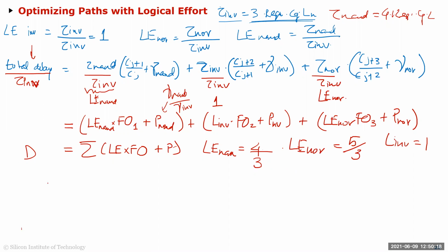If you want to measure it, there are ways to actually measure it. There are 2 ways to find the logical effort for gates. So let's say you have an inverter, right? You size this inverter, this is 2W, this is W. If you want to do it by simulation, or even by calculation, you want to set the delay of the inverter. So for example, let's take an example of a NAND gate.